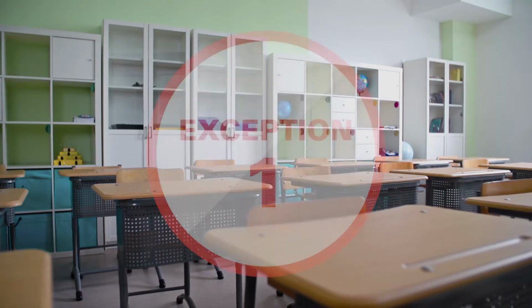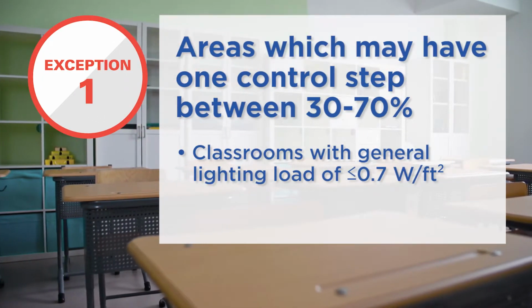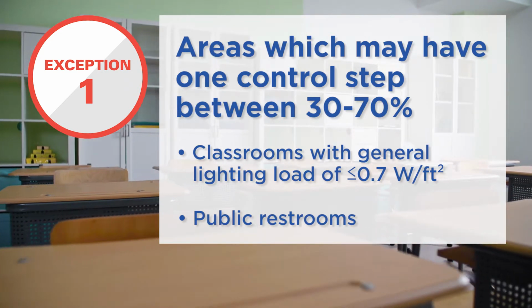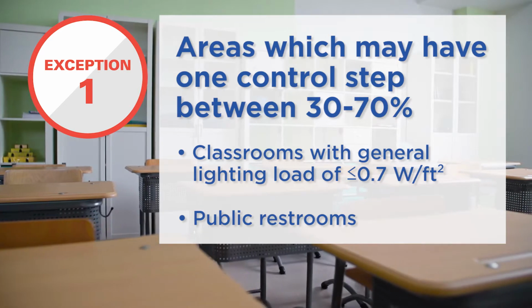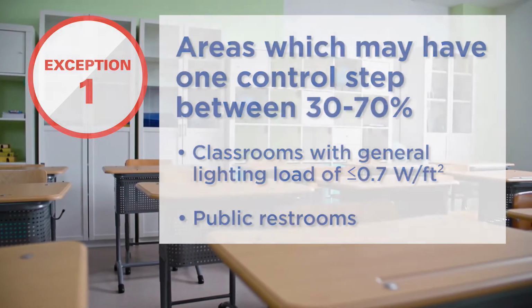However, there are a few exceptions to the multi-level control requirements. Classrooms with a connected general lighting load of 0.7 watts per square foot or less and public restrooms need only have one control step between 30 and 70% of full rated power, regardless of source type. Of course, more control steps can always be added.